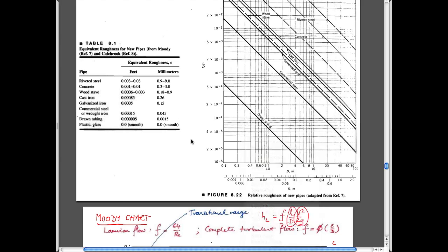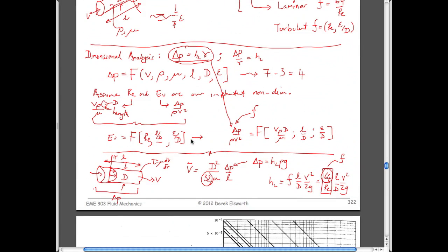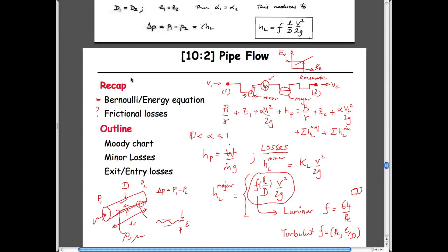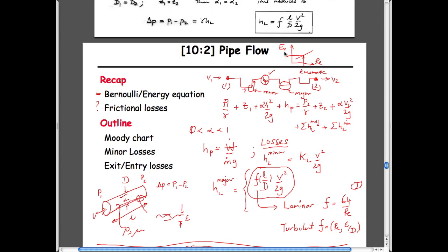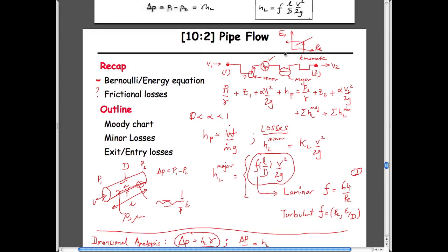And it goes back to the simplest expression that we made, that we conjectured these are the appropriate variables that describe behavior. We conjectured that the flow regime changes with Reynolds number, and therefore with Reynolds number the pressures acting between upstream and downstream should change, and those pressure changes should be in some way indicative of the frictional losses within the pipe.